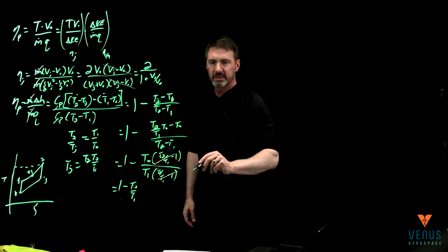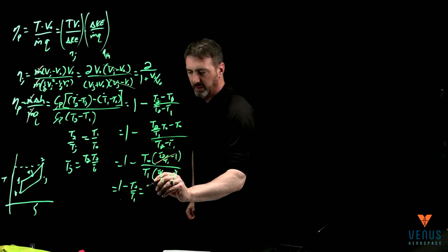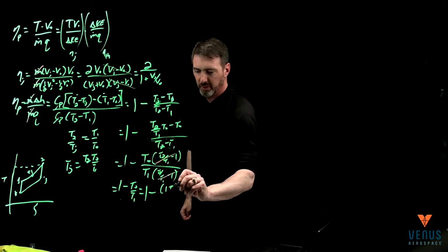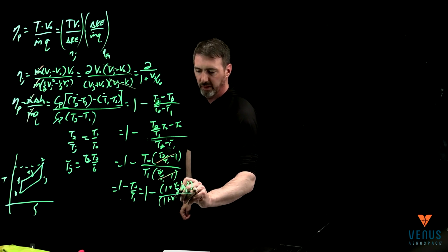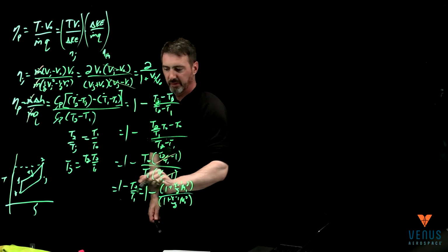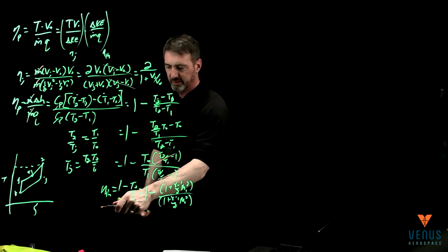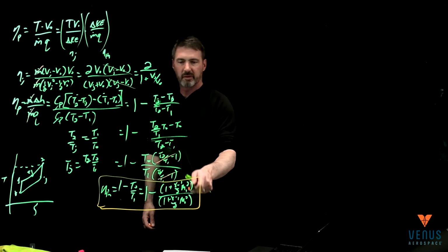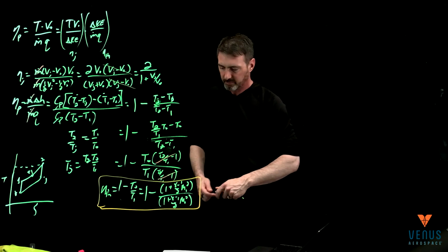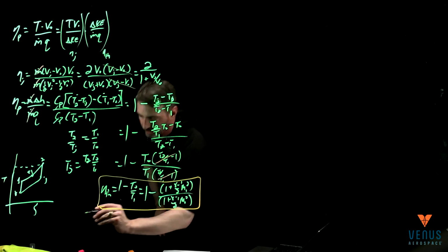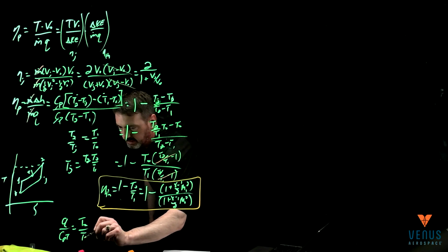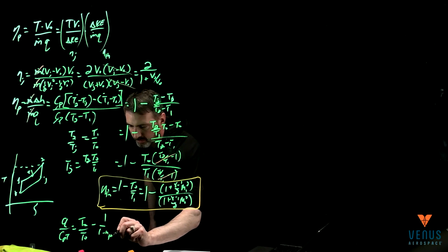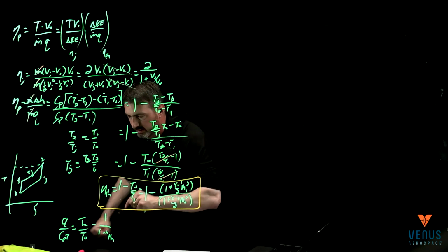And we showed last time that's basically 1 plus gamma minus 1 over 2, Mach 1 squared over 1 plus gamma minus 1 over 2, Mach 0 squared. And so, as a reminder, this is eta thermal. And so eta thermal is simply set by the speed you're combusting at compared to Mach 1. And then we had another equation for the amount that you can add, which is set by your maximum T2 over T1 minus 1 over 1 minus eta thermal. And so that's how you find what you're able to add.